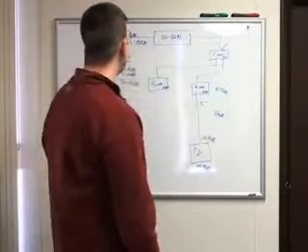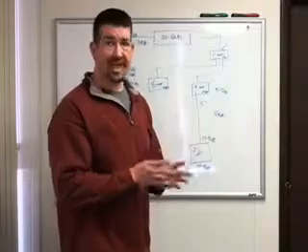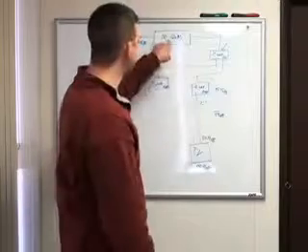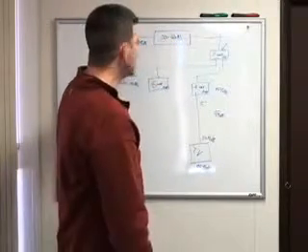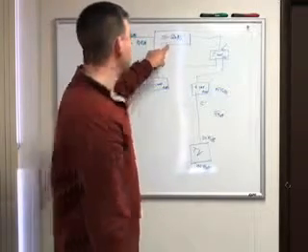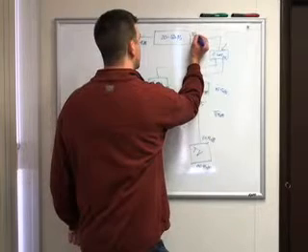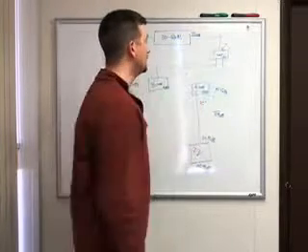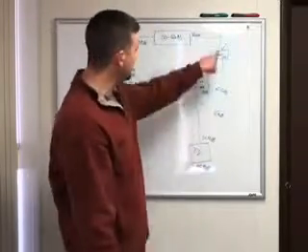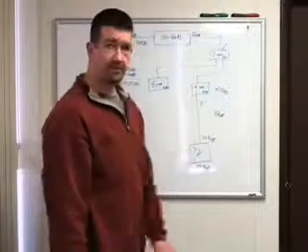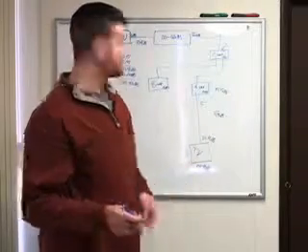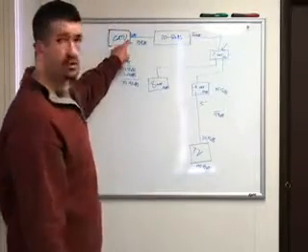So if we adjusted this down to 20 dB, and again, this is gain. So whatever you have coming into this amplifier, gain means it's going to add this amount of signal on top of it. So if we have 6 dB coming from the cable company, and we have the amplifier adjusted to 20 dB, on the output of it, we would have 26 dB, which is about half a dB more than what we calculated we need at the input of the amplifier of 25.41.